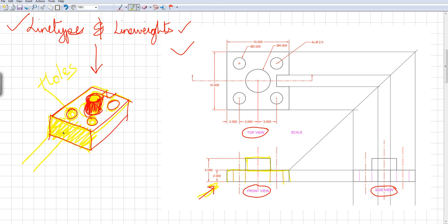Okay? I'm not seeing the top surface. All I see is up till here, and I don't see this. Why? Because this is a normal surface, right? And then I see this part, which is the cylinder. So I still want to show someone that there are these 4 holes that exist. So using these hidden lines, I could show them that there are holes, right?